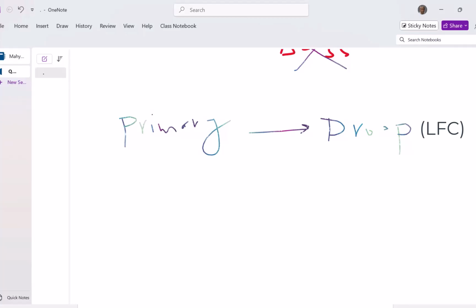If there is a reduction in the load in the system, the first object in the system to tolerate that would be the inertia of the generator, to basically absorb that extra power into itself so that the frequency boosts temporarily. Okay, so that's called the primary control, and that usually gets handled through the droop line that we just talked about.